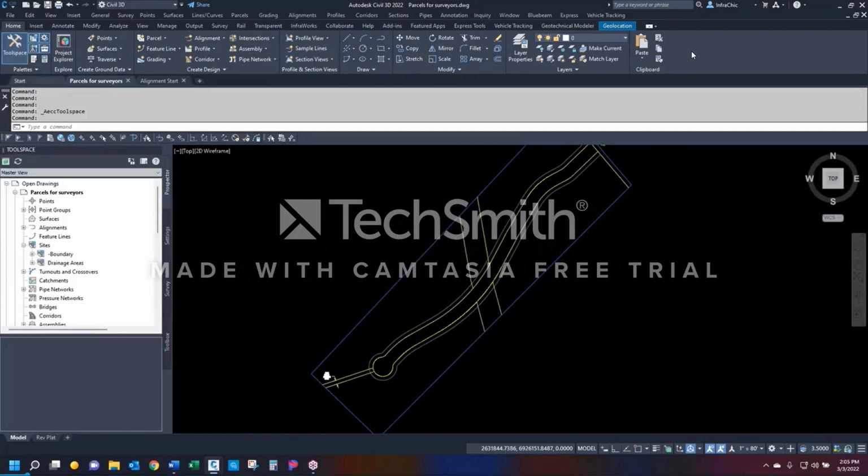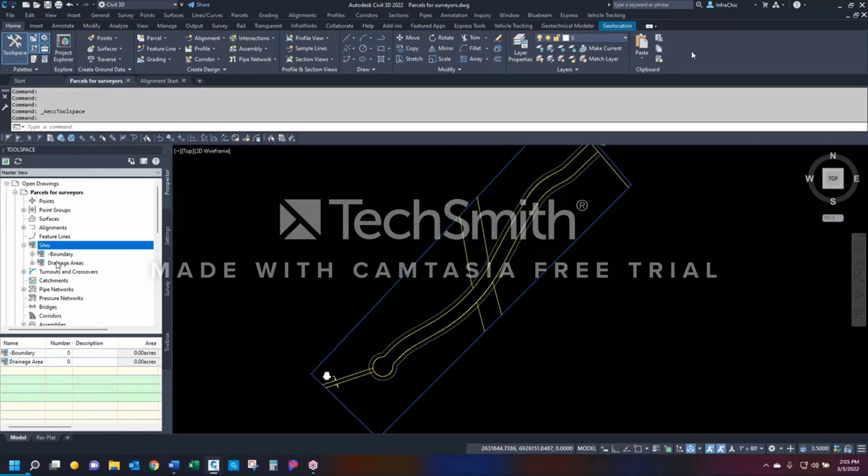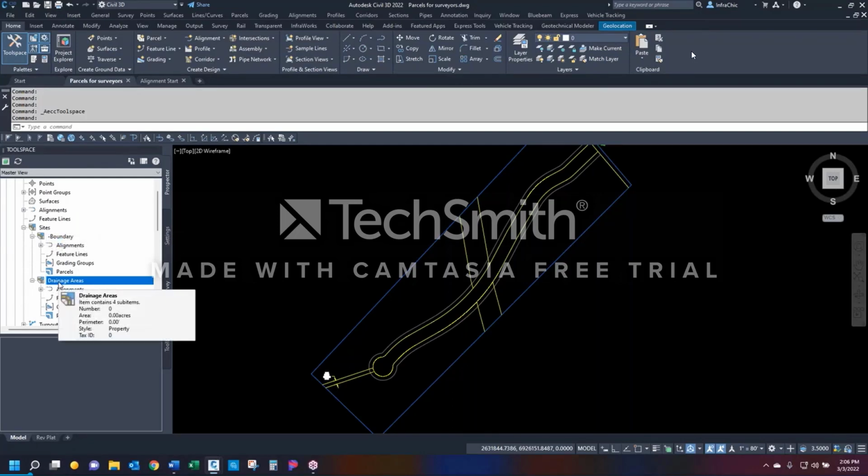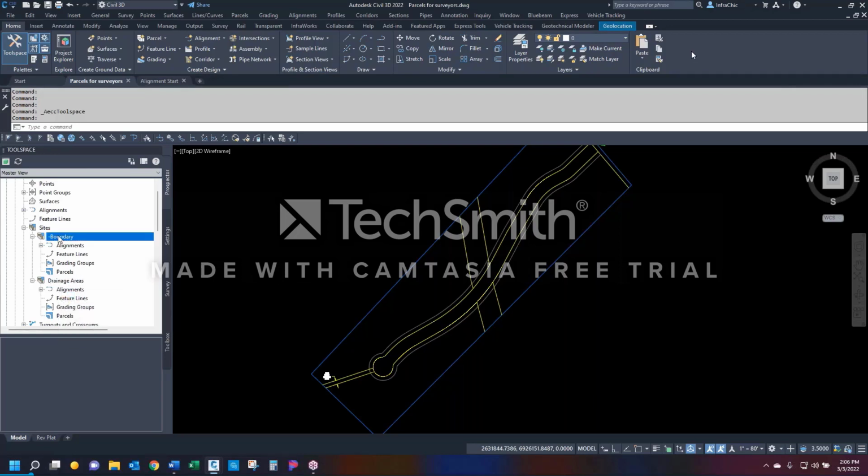Okay. I've expanded sites down here because I took out some sites, but I want you to note that I already have two that were created by myself some time ago. I have a site for boundary and a site for drainage areas. When I make a parcel, I have to choose which of these two sites they go into. Now, as a civil designer, I will use drainage areas in both my existing file and in my proposed file. But as a surveyor, I will never do drainage areas. Just keep that in mind. On the other hand, I will do boundaries. And I will probably need other sites, which we will make after we deal with the boundary part.